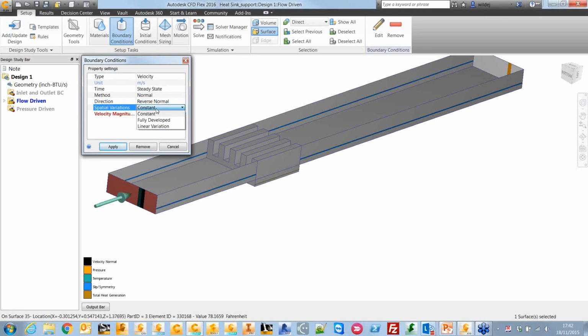If you go to one of the volume flow rates, yeah, even for velocity, that makes it so we don't need as long of an extension. If you look up the equation to calculate it, it ends up being monstrous. If you were doing pipe flow, you'd need like 25 to 50 diameters extra. I don't think that's perfect, but it can help. We've got a case where we're looking into that right now. Something goofy's going on.